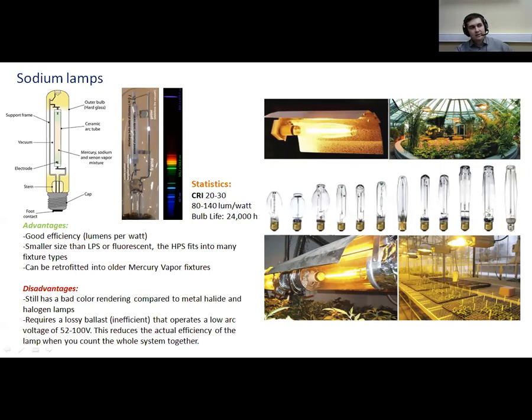The electron impact ionization coupled with the thermal ionization results in electronic jumping to various higher energy states. So it means that after this process, the electrons relax to the ground state, and after that, electrons emit electromagnetic radiations. This radiation covers a wide spectral range, especially in the visible spectrum. So HPS lamps have become a popular source of electrical lighting in public spaces and industrial buildings.